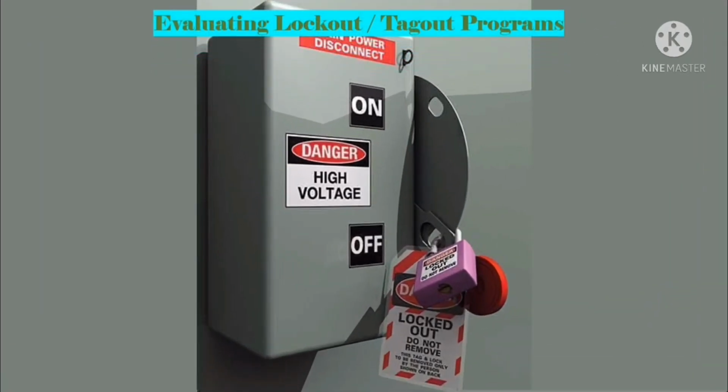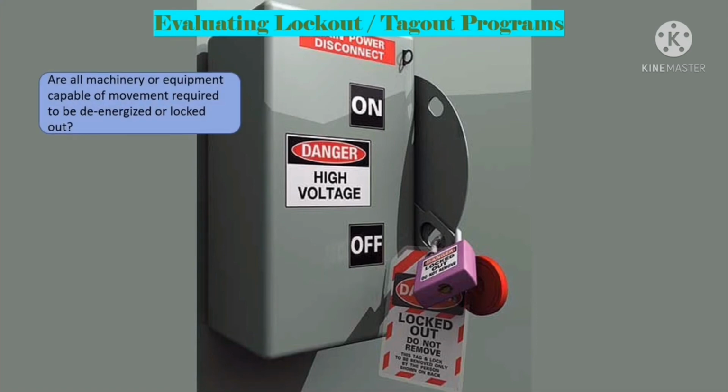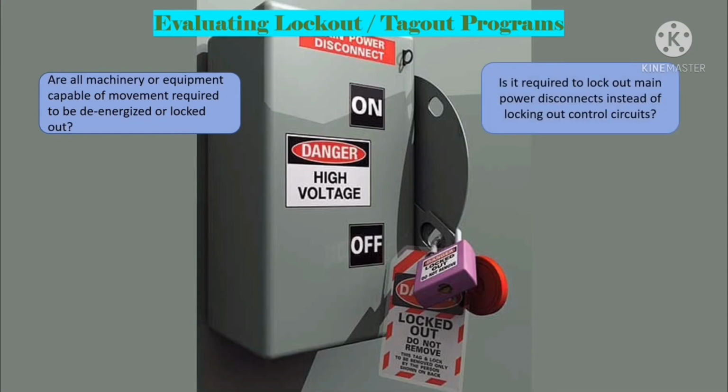Next, evaluating the lockout or tagout program. Firstly, is all machinery or equipment capable of movement required to be de-energized and blocked or locked out during cleaning, servicing, adjusting, or setting up operations? Secondly, is it required to lock out main power disconnects instead of locking out control circuits?